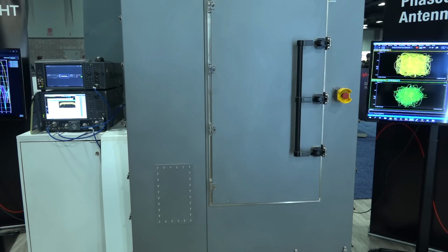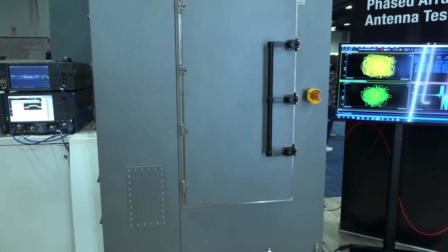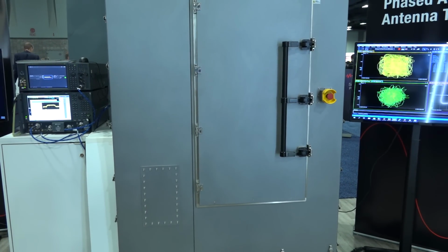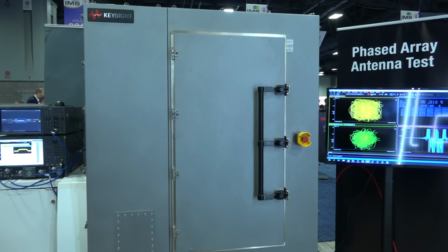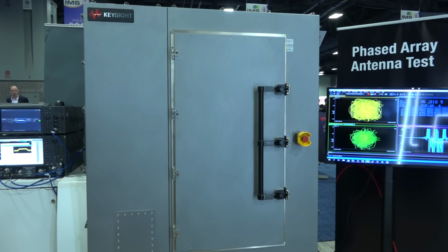And here we have Keysight's antenna chamber characterization. I think this is the first time I've seen that at the show, that they brought this entire thing. This box is supporting up to 110 gigahertz, but the fundamental principle is the same. It's doing near field to far field translation with a reflector inside the box, which we will see in just a moment, and it allows you to calibrate up until the surface of your array or your transmitter.